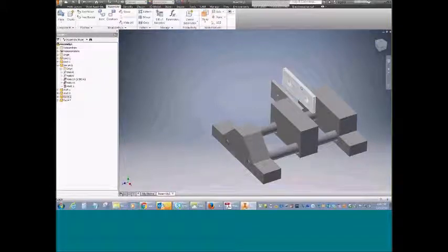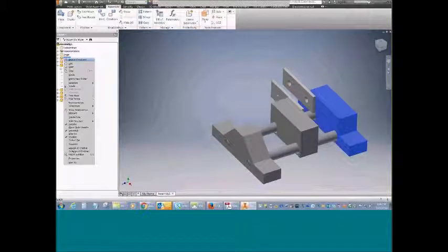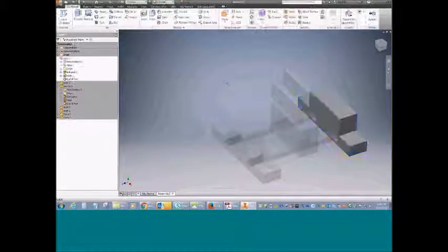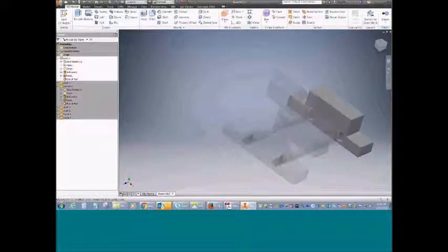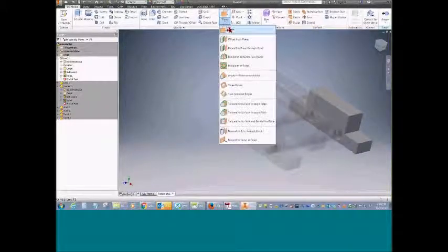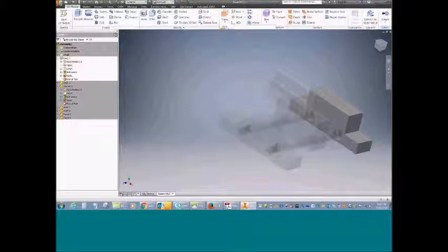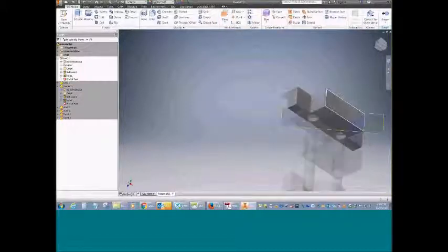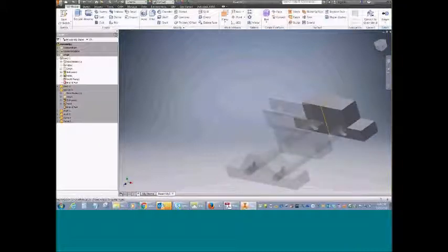So if I want these jaw plates to be centered on these aluminum jaws, I'll show them that they can, first of all, edit their parts in the assembly, so I don't have to leave the assembly to edit that. I get ghost images of my other parts there, but I'm just going to put a mid-plane in here between that surface and, orbit around here, that surface.